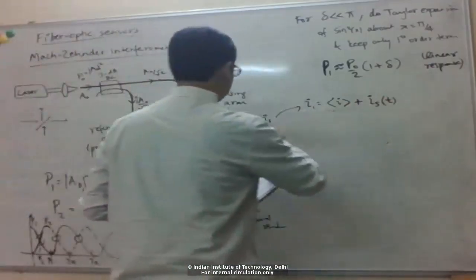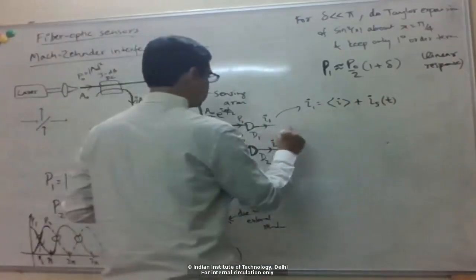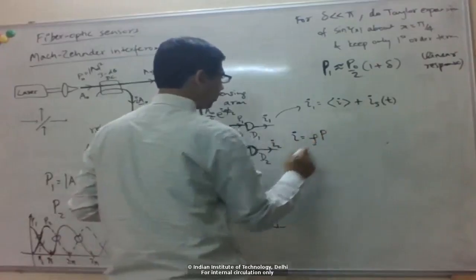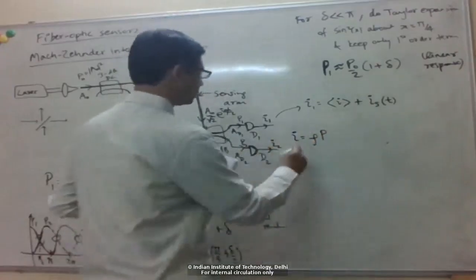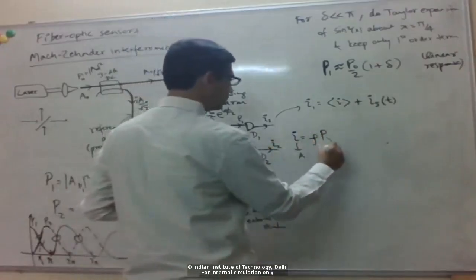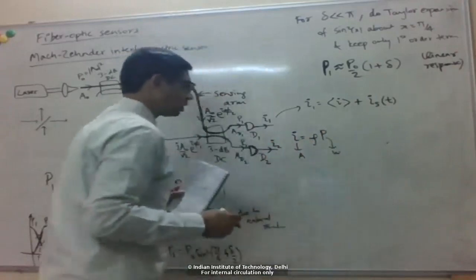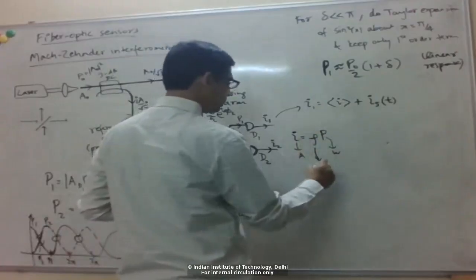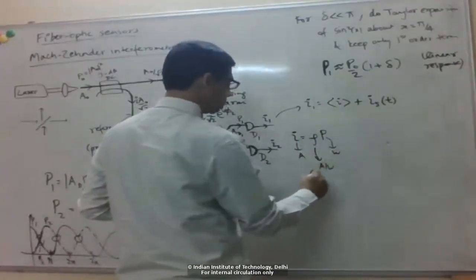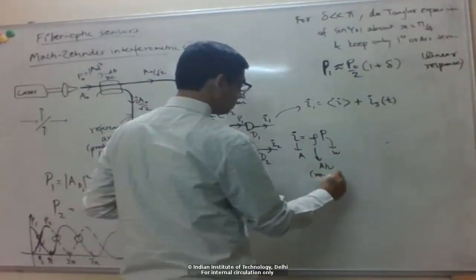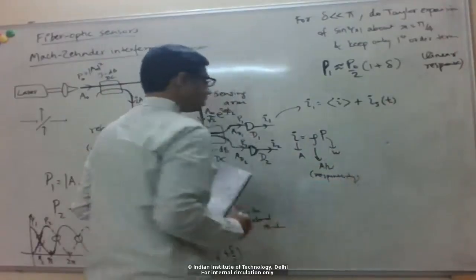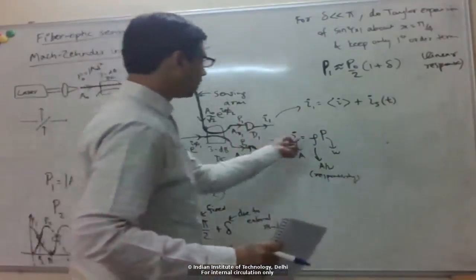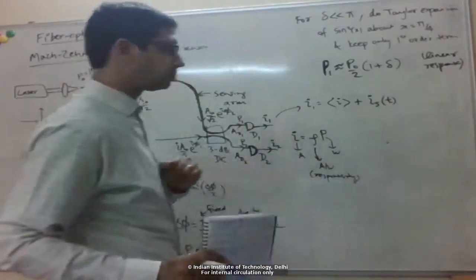So the photodetector basically gives a current which is proportional to the optical power. Okay, so this is current in amps. This is the input optical power, let's say in watts. So then there is a constant of proportionality here, whose units you can see are amps per watt. So this is known as responsivity. So rho is the responsivity of the detector, which gives me a certain current for a certain amount of optical power.